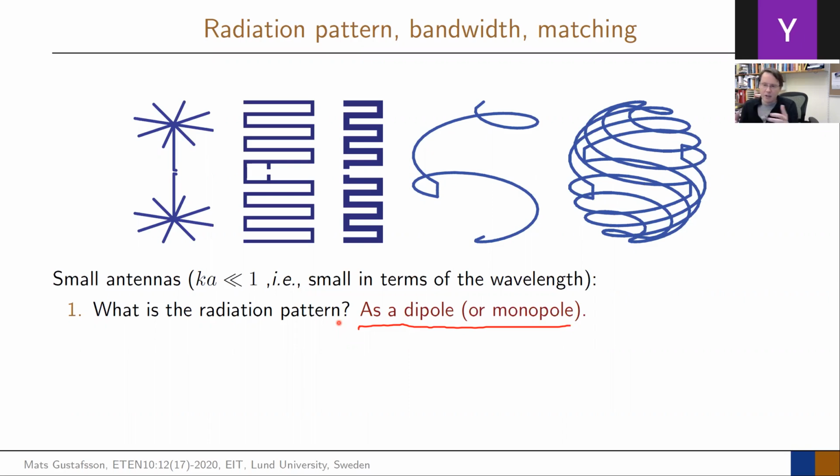So if you have a regular dipole, it's like 1.5 maximum directivity. If you combine electric and magnetic, you can actually go up to 3. So there are quite some attempts to do that. But it is a typical dipole pattern, so this donut that you have. That's a typical pattern when something gets small.